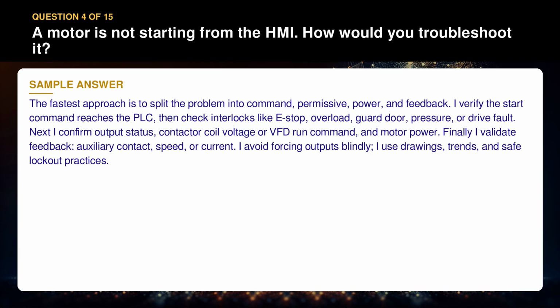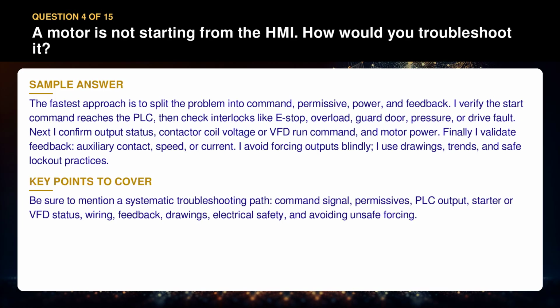I avoid forcing outputs blindly. I use drawings, trends, and safe lockout practices. Be sure to mention a systematic troubleshooting path: command signal, permissives, PLC output, starter or VFD status, wiring, feedback, drawings, electrical safety, and avoiding unsafe forcing.